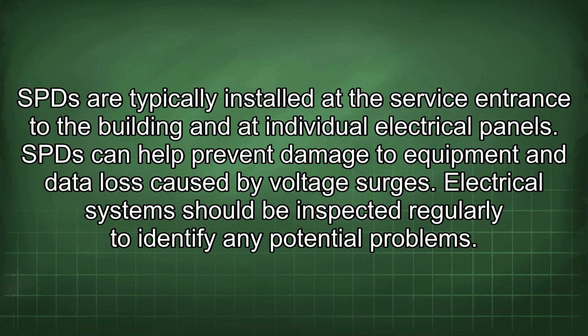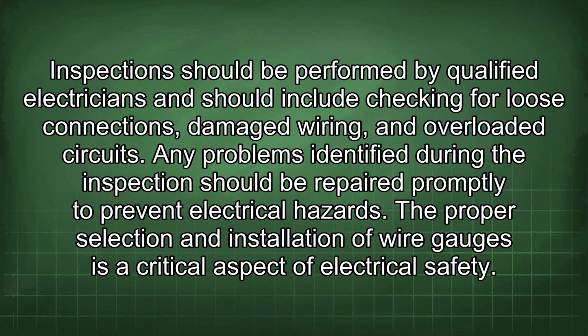Electrical systems should be inspected regularly to identify any potential problems. Inspections should be performed by qualified electricians and should include checking for loose connections, damaged wiring, and overloaded circuits. Any problems identified during the inspection should be repaired promptly to prevent electrical hazards.